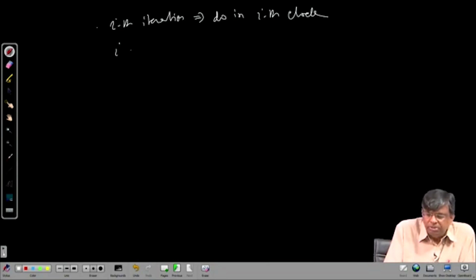So, I replace i by n, because normally n is the letter that is used typically to indicate a clock, nth clock or nth index, not ith index. So, at nth clock we carry out nth iteration. I prefer n rather than i, so I replace it by n. So, in that whole iteration you are looking at the waveform at nth clock, you are doing the nth iteration, that is from W n you are going to W n plus 1. Then at n plus 1th clock you are doing from W n plus 1 to W n plus 2 and so on and so forth. All right. So, we are running in real time.